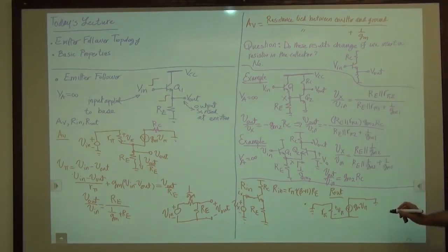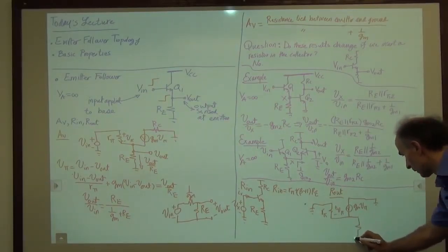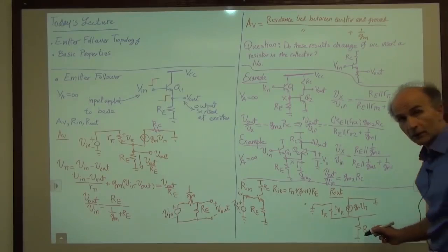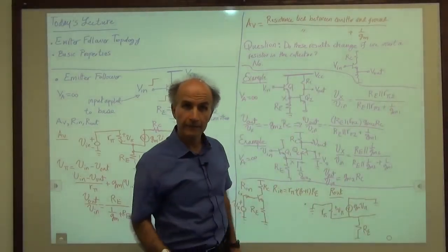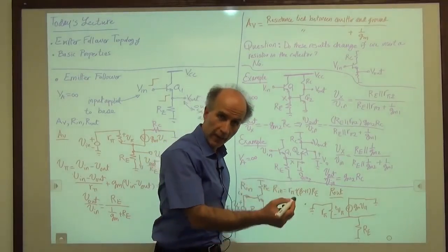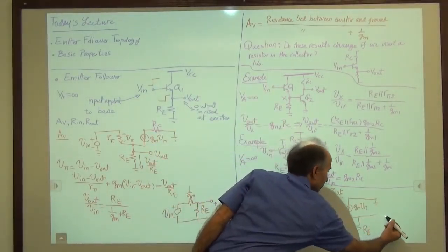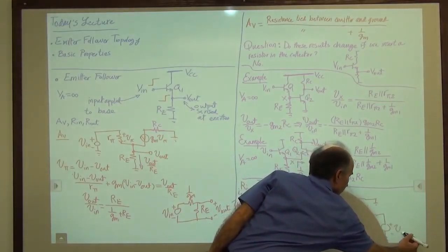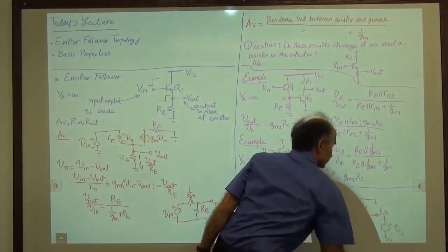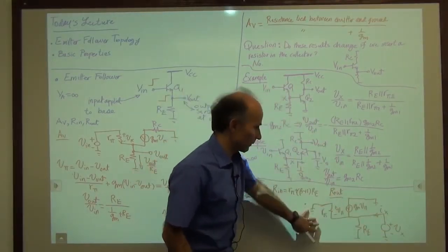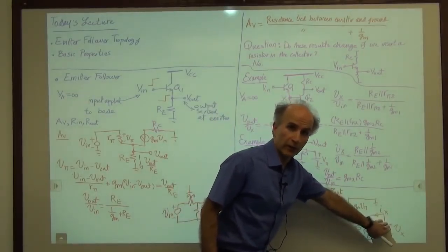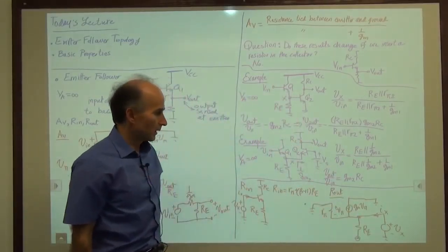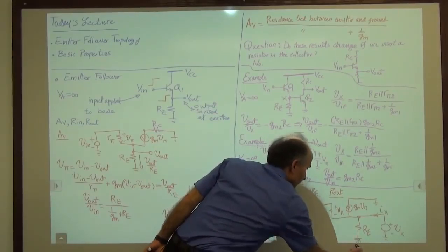Okay. All right, so I will draw RE over here. RE. That's okay, right? So far I haven't done anything illegal. And now I go ahead and apply Vx and measure Ix. So I have to apply Vx here, and measure Ix here. Right? We said we put the whole circuit in a black box, and we go to the port of interest, apply voltage, measure the current. All right, no problem. So that's what we have. Okay, and remember that RE is connected to ground.